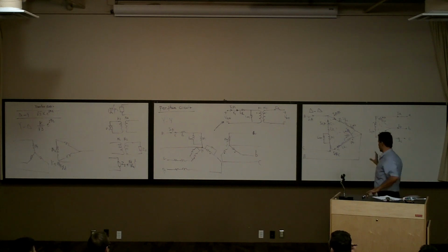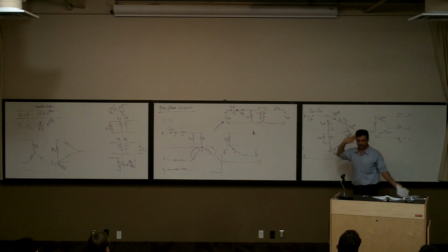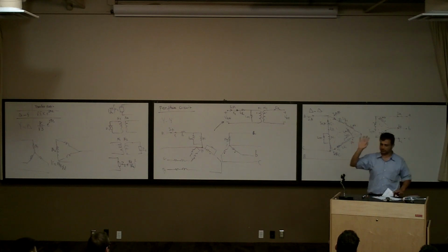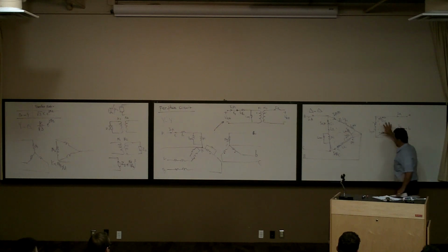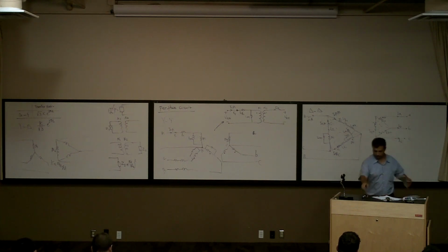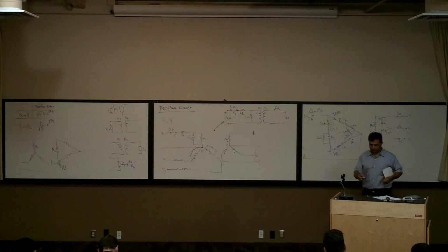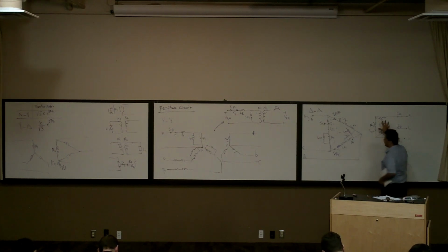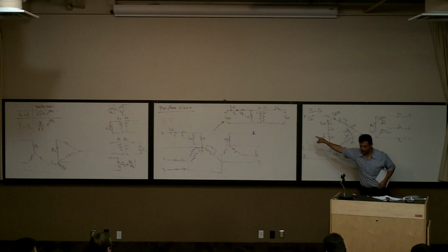So basically, if I'm going to redraw this one, it is going to be R1 over 3, LL1 over 3, LM over 3, and N1 something, right? N1 either times the square root of 3 or something, you know? That one doesn't matter. Why? Come here. This is N1 and this is N2. N2, N2, and N2. So when we come here, we are going to convert this one also to the star, right? Do I have any impedance here to be worried about? No, because I put all the impedances on my primary, right?